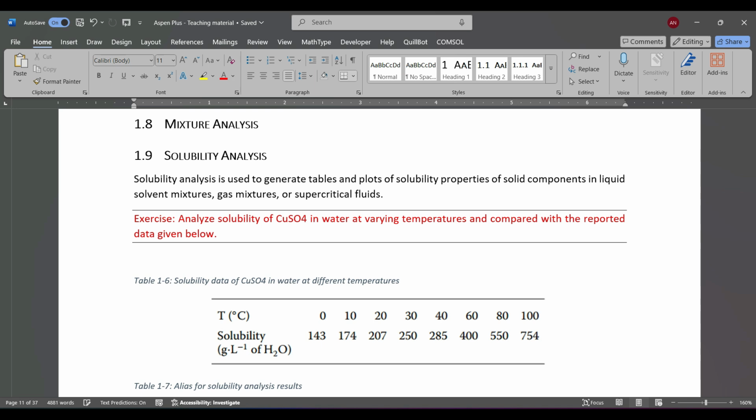And these are very special cases if we are dealing with, for example, crystallization, because crystallization starts when we have saturated mixtures, and that saturation is not related to humidity saturation, but this is about solubility or solutions. If we have more solute than the solubility limit, that is the perfect case to do crystallization and get the solid out of the solution.